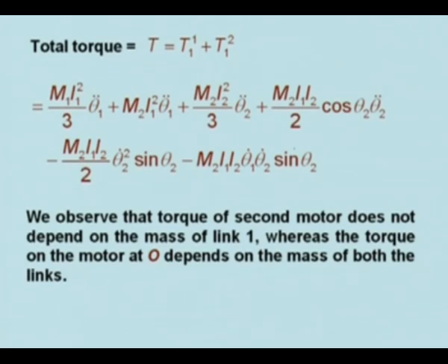You can just differentiate and get the value. In some cases you may be prescribed the torque and have to find the angular displacements. In that case the inverse procedure has to be done. You have to do some sort of integration, because this then becomes a differential equation which has to be solved. So numerical methods can also be used.